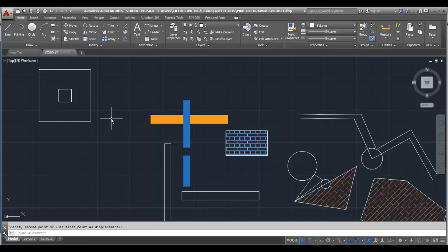You'll notice that when we're drawing just regular lines, left click, it gives me distance and angle. Gives me a polar coordinate. So if I want to put in a line that's 6 units long, hit the tab key, and I want the angle to be, let's say 10 degrees. There it is. 6 long, 10 degrees off the 0 axis. So this is 0, 90 would be straight up, 180 would be to the left, and then 270 straight down. You can also use negative angles if you want in here.